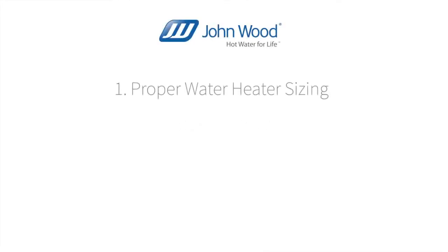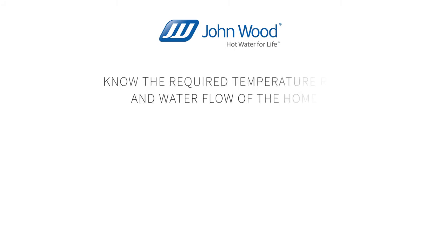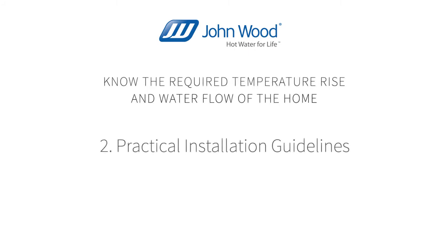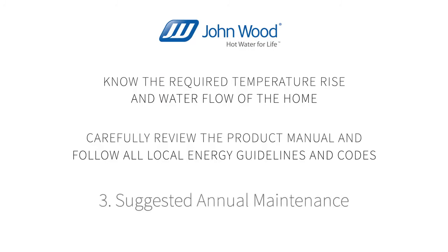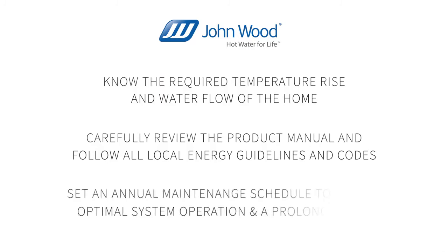In summary, when you are choosing the right tankless water heater for your application, it is very important to remember the following tips. For proper sizing, know the required temperature rise and water flow of the home. During installation, carefully review the product manual and follow all local energy guidelines. Finally, set an annual maintenance schedule to ensure optimal system operation and a prolonged life.